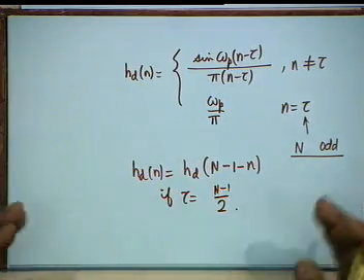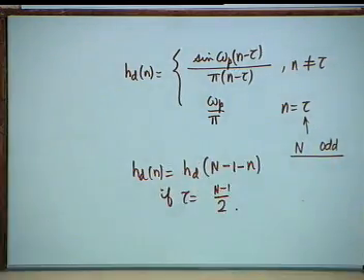Okay. So, we have closed our options from both sides, so that we are sure that the design that we are aiming at shall have a symmetrical impulse response. In other words, it is guaranteed to be linear phase. Otherwise, we are not interested in finite impulse response, because we can do with much less hardware if we aim for IIR.